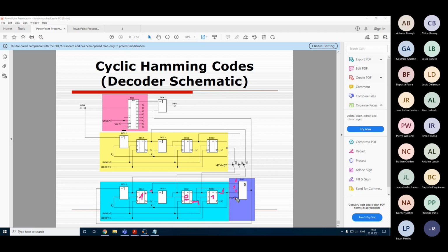And here we also connect to 1, basically a voltage of 1, for example 5 volts. Because in my particular case, I have a 4-input AND gate, and I need to send 1 to each of them. This is always 1, and these 3 are read from these flip-flops. First and third are read from the direct output, and the last is read from the inverse.